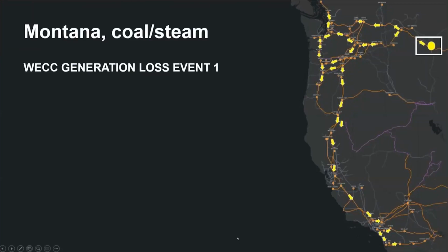So let's go ahead and look at some of those events and show you the propagation of those events. So here we're taking PMU data again from several different locations within the Western interconnection from different utilities, and that information is brought together. And for the particular event, we then run that data through the algorithm. And what it gives us is the ability to map out the propagation. So you can see the big yellow circle is representing the closest location where we have a measurement for this particular event.